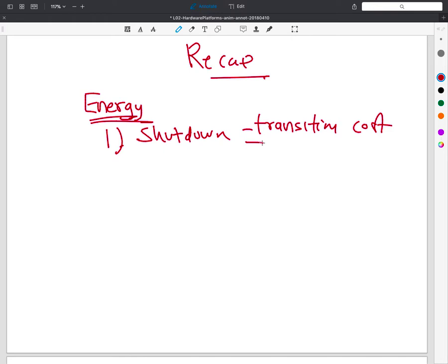The second aspect was that I talked about how systems themselves, the hardware itself, provides multiple modes, and we had used the processor, which is on Hexaware, as an example, that how it had a whole bunch of states. Generally speaking, as you might expect, the deeper the system goes into sleep, so to say, that is more reduced functionality, then of course the more benefit you get in terms of energy, but you also pay the penalty of it takes longer to come out of it.